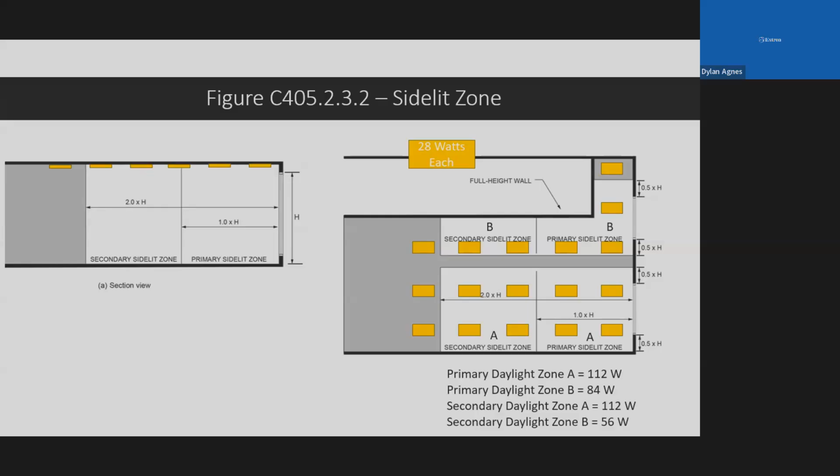I don't recommend that because that's kind of a way to reduce the number of sensors in the space. But again, if you increase the amount of sensors, you increase the amount of data, which increases your resolution, so you understand what's going on in the space. And as the sun moves throughout the day, it changes from east to west. So those levels are different. So you want those zones controlled differently because the daylight levels are different.